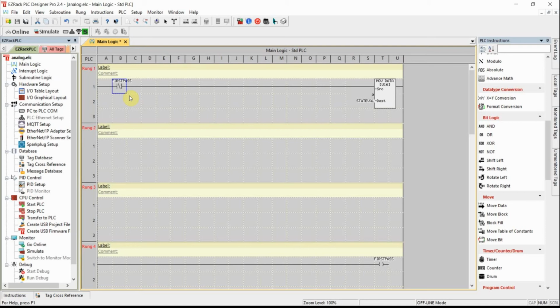Because right now it seems fine to have it reset to 0. However, it could be that your system is processing products, and if it goes back to 0, it causes scrap or damages itself. So there are a lot of considerations to be made. I think for right now, we're just trying to have a system that starts up in a known condition. And a manual reset would be a great way to go.